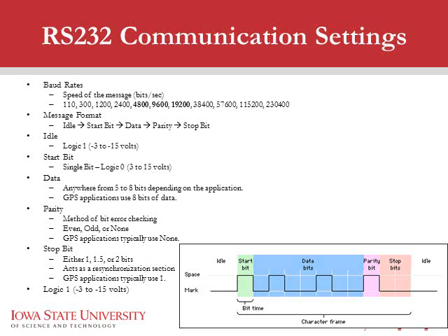Just like we've had to set up many different types of communication protocols for RTK, the same thing exists for RS-232 communications. In this case, we've got a variety of different indicators. Baud rate indicates the rate at which the messages are transmitted. This means the speed at which each bit or piece of information is sent. Typical baud rates that we use in agriculture are 4800, 9600, and 19200.